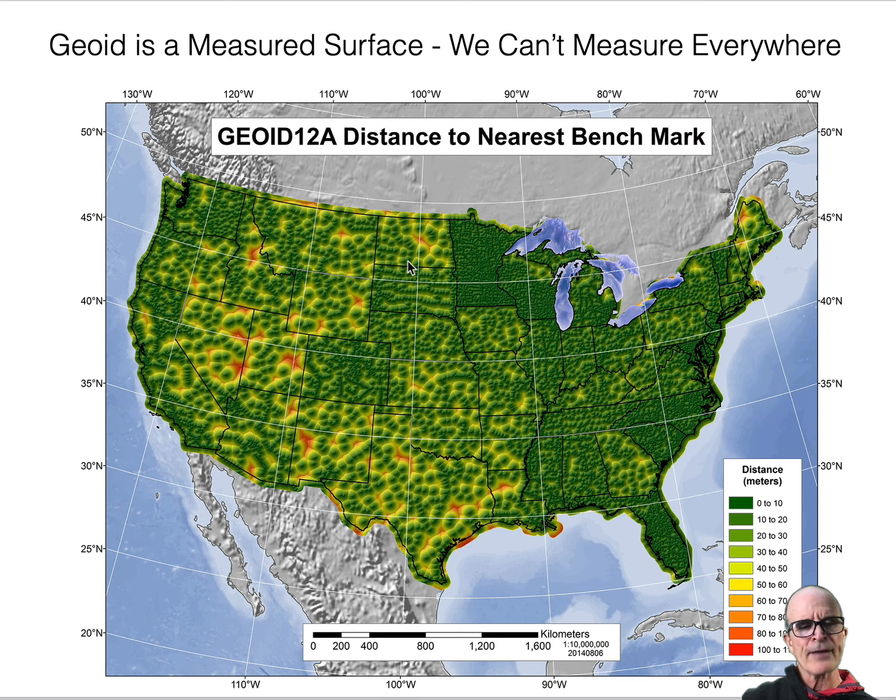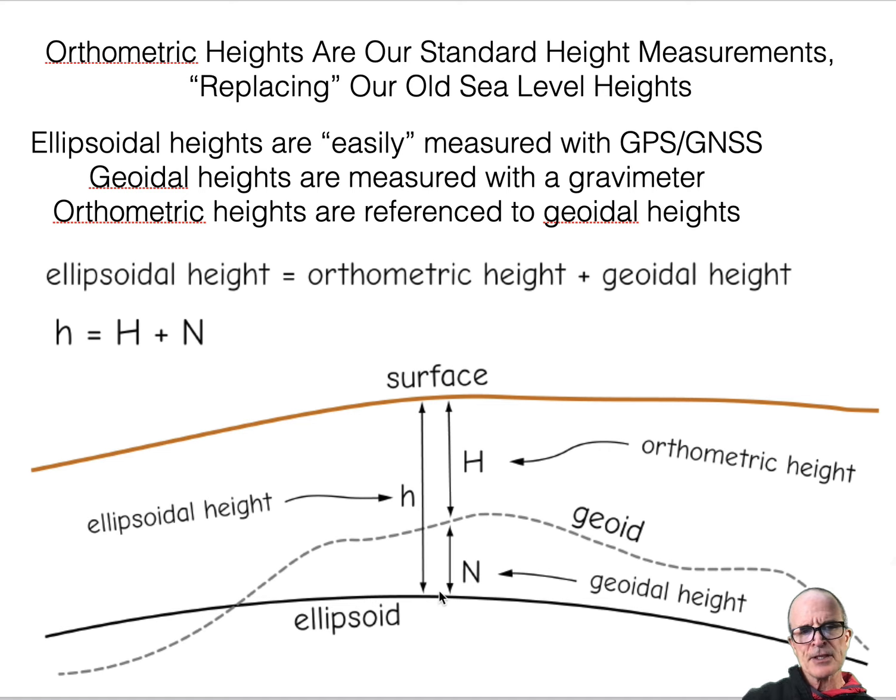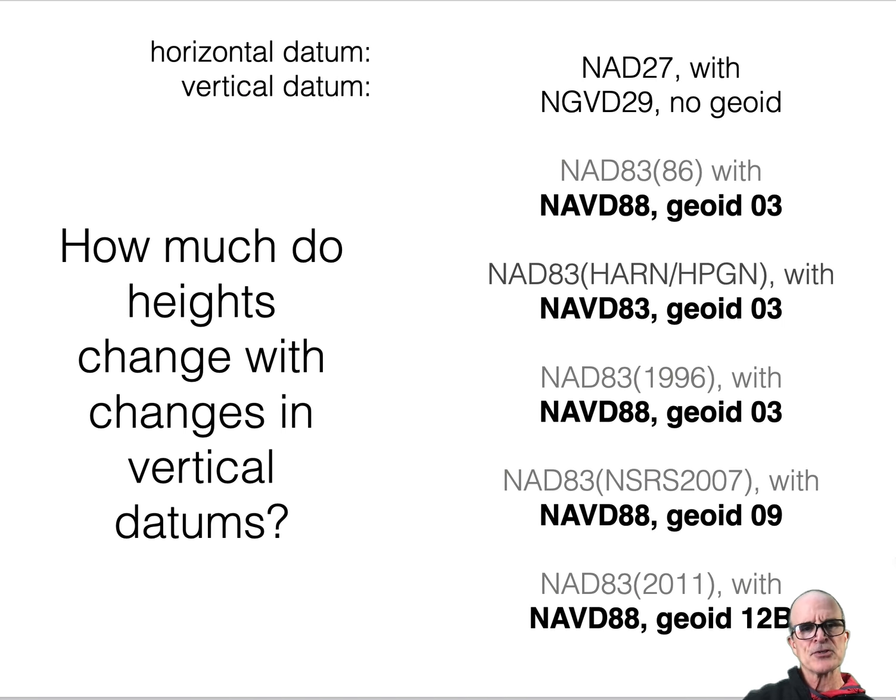Right? And so they really don't have as good a vertical datum, but nonetheless, it's fit and the geoid is provided for you. If I know the latitude and longitudinal location from GPS, I can get the geoid height above or below that spheroidal surface. I can actually look up this distance, right? And then once I get this distance, I can estimate what this distance is from the GPS measurements. So we have a set of measurements.